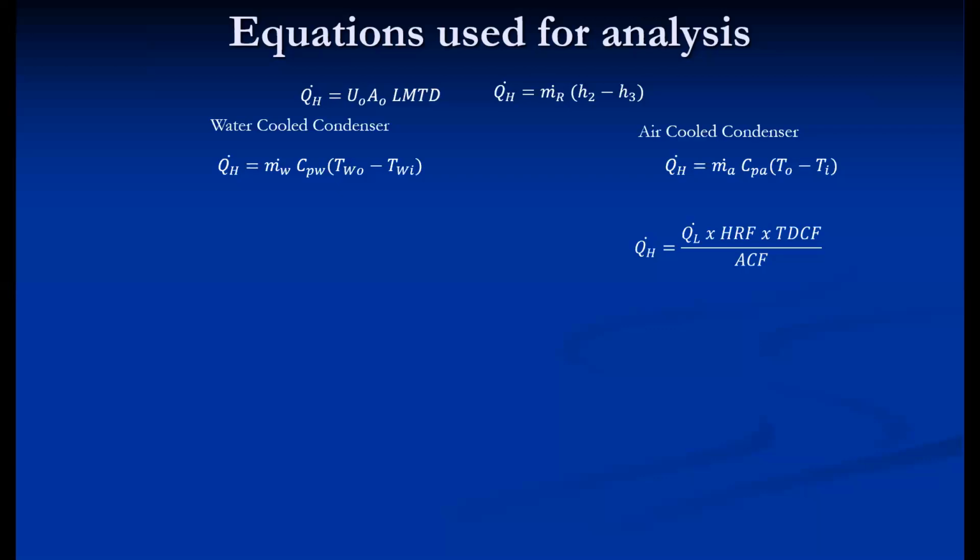That correction is generally given in numericals also, or in a table. Altitude correction factor mainly is required because at ground level, if the condenser is used, then the altitude correction factor is generally considered as 1. And if it is used above normal sea level, then the correction factor decreases. So as the elevation from sea level increases, the correction factor decreases.